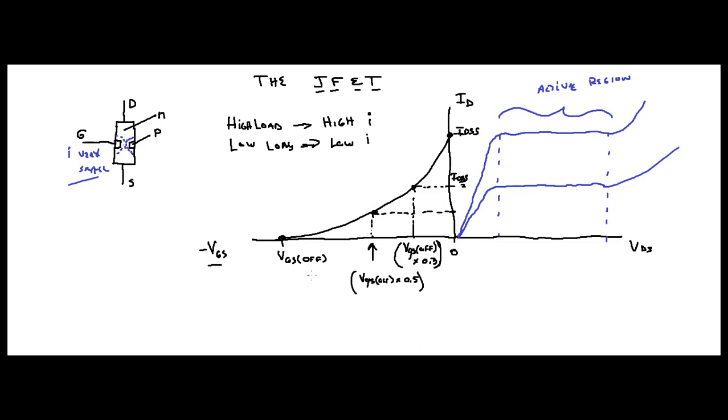What happens if VGS changes and now you're going to be at IDSS over 4? Draw that right here. It's getting kind of small there. Well, what's going to happen? We're going to come over here, aren't we? Then it's going to level off here, isn't it?